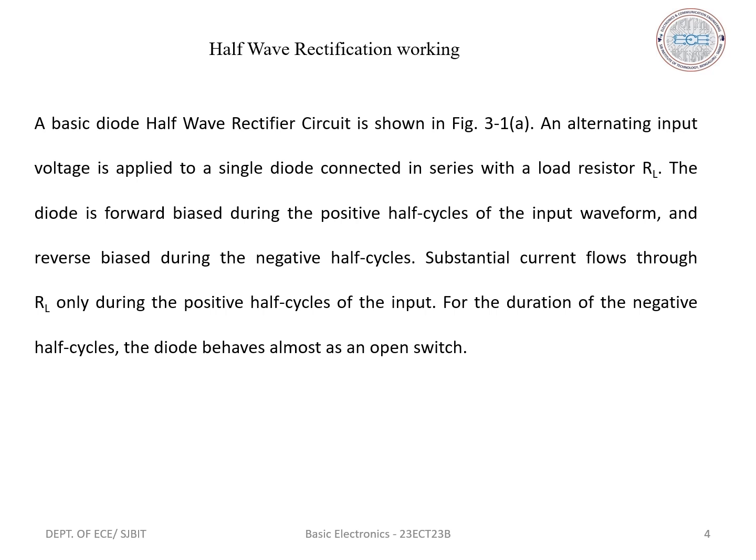And also we have rectifier efficiency. Rectifier efficiency is defined as the ratio of DC output power to AC input power. It is given by the equation eta equals PDC by PAC into 100. Next we have the ripple factor. It is defined as the ratio of RMS value of the AC component to the RMS value of the DC component. So the ripple factor equals VAC by VDC.